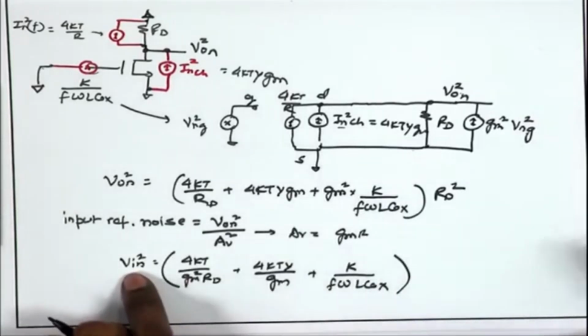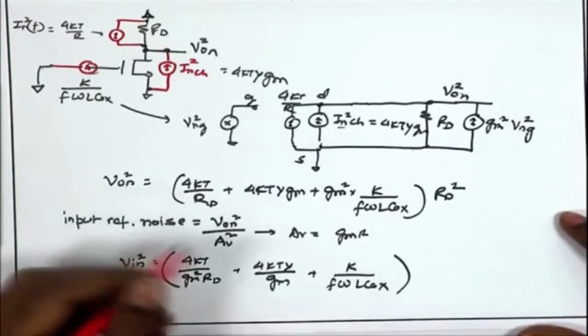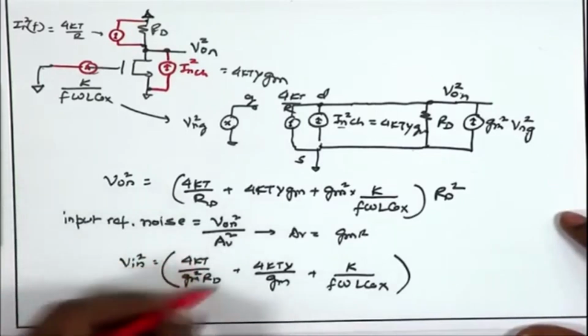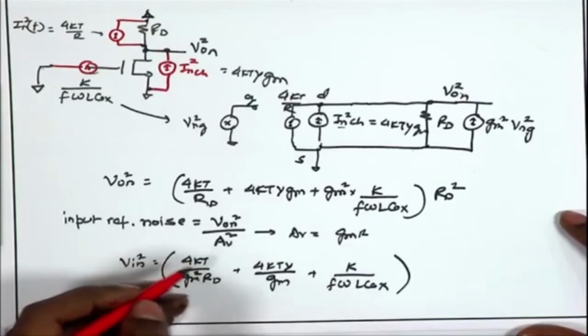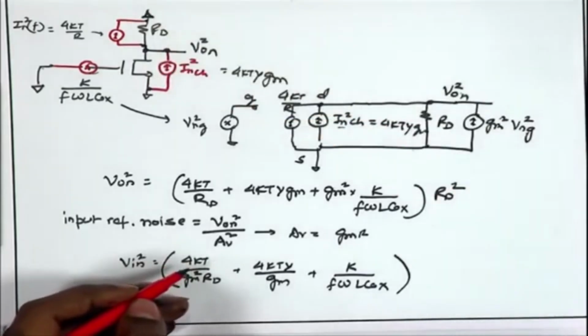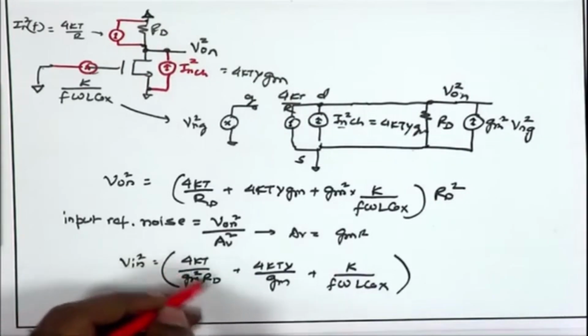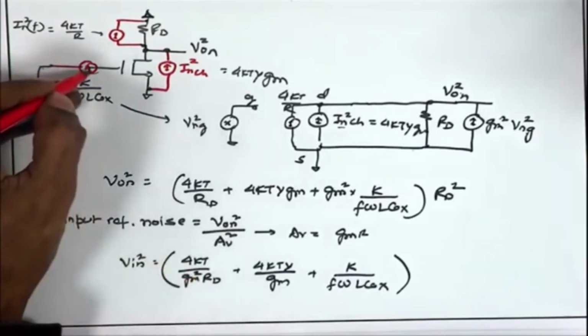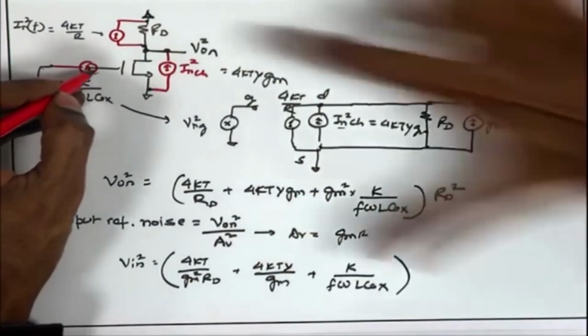And we see some interesting results. We see that the input referred noise is inversely proportional to RD. We would expect that if RD is large, its 4kTR noise voltage will be large, but here we say that input referred noise is lowered if we increase RD. Why? Once again the same phenomenon, because larger RD also amplifies the input signal going to the output.